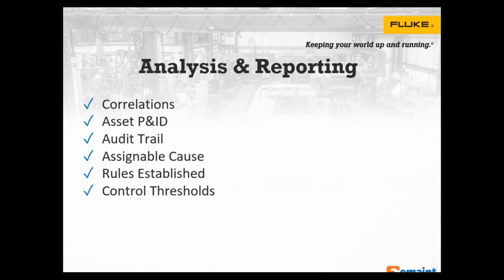Okay. With what we talked about earlier in those control charts, you can set the limits based off mathematics, the SPC type of math. These programs are available out there. But really, the control thresholds can be set based on the data, but sometimes it could be straightforward, where it's the operating limits of that particular asset.